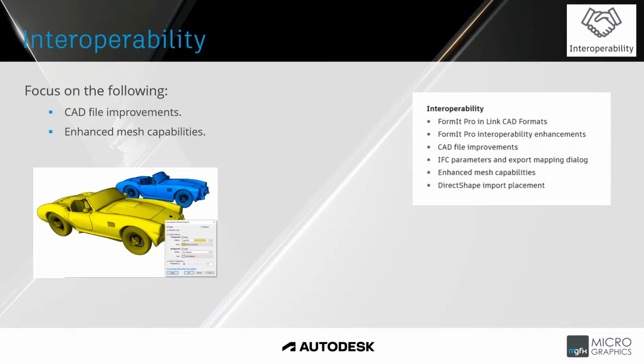The mesh capabilities, also I had a look, specifically a SketchUp import, and what's nice about the SketchUp import or the OBJ imports and various other imports, you can actually then override the lines, the particular edges. You can override their colors, and in so doing, the mesh is overridden in its color.